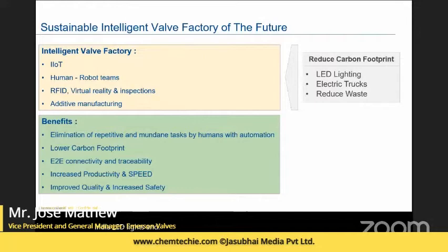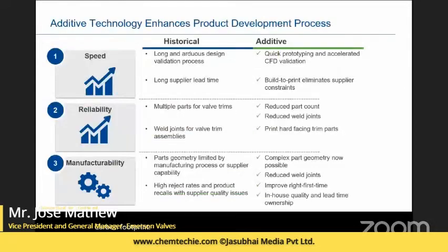And then if I move forward to some specific topics, let's talk additive technology. These are being employed by some of the valve vendors already, and there are two segments to it. One is, as we all know, most of the valves have body and bonnet, which are castings. To make the molds for the castings, we can employ 3D technology, which reduces the lead time to develop those patterns of the molds.